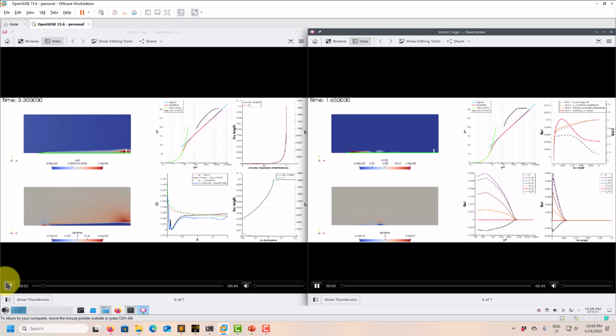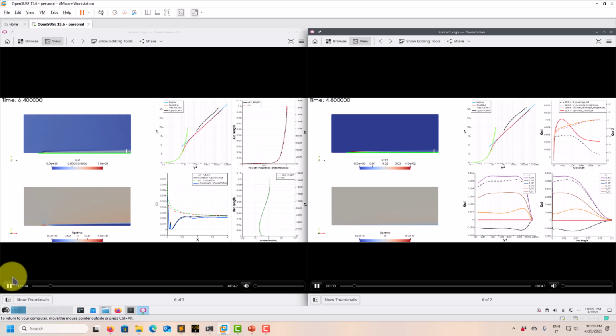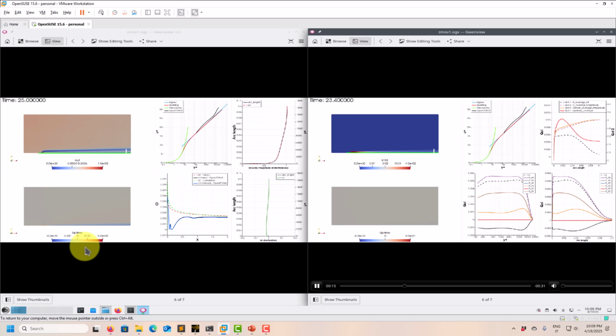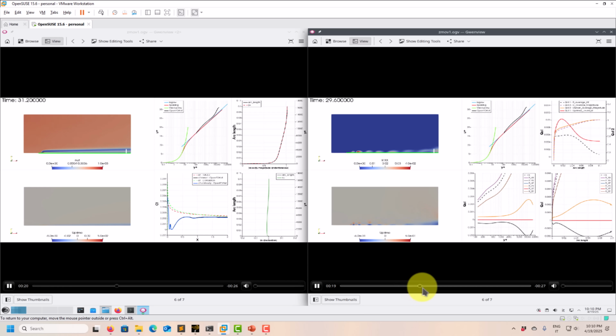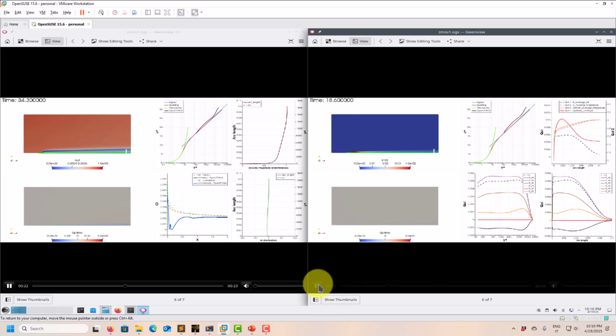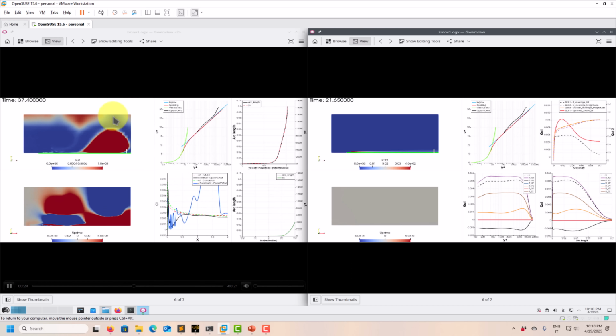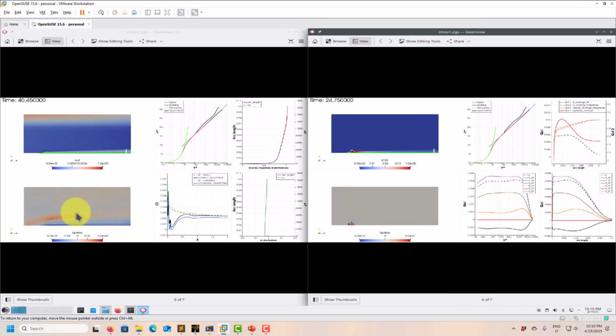Play, and look at what we have here. And there you go. Immediately the Reynolds stresses are dissipating, everything is mirroring all the fluctuations. Now, I will say presumably this is due to the effect of the wall echo. Okay? Requires some study, but very interesting. You dissipate, and at one point, and also in this case, boom, you have again the onset of the instability.